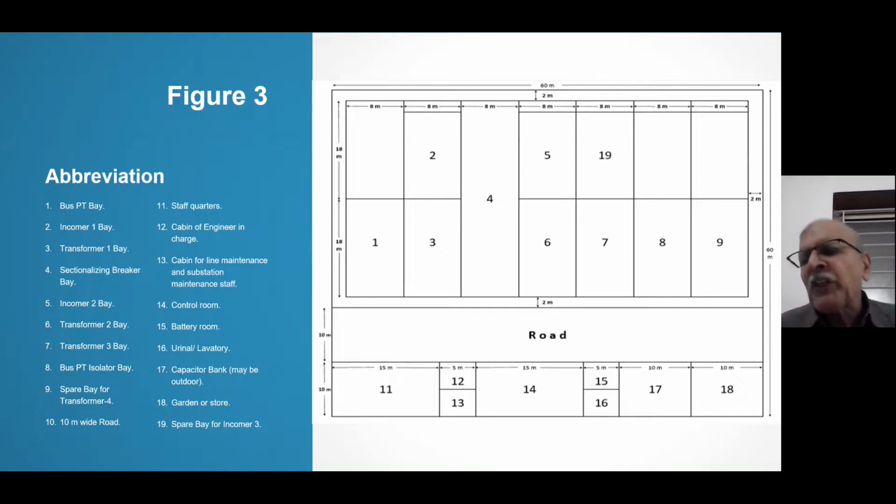You see, complete control, breaker making on and off or any control is through DC. You cannot depend on AC. No doubt, usually you are converting AC to DC using rectifier. But if AC is lost, that means both the two incomers are lost, then you will lose the control. Control is the heart. You should not lose the control. So you will be feeding controls through 220 volt battery. So that battery room is there. That 15 is battery room.